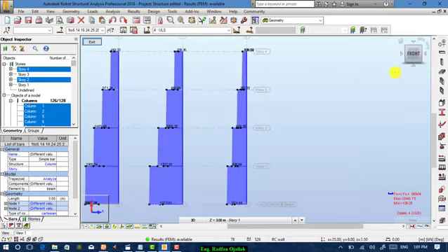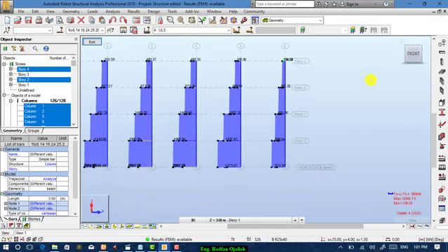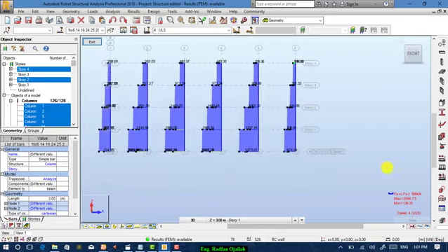As it's shown here, forces increase on columns as we go down. That's why columns cross sections decreases as we go up. And it's also shown here the maximum axial force on columns, that is 2046 kilonewton, and the minimum is 193 kilonewtons.